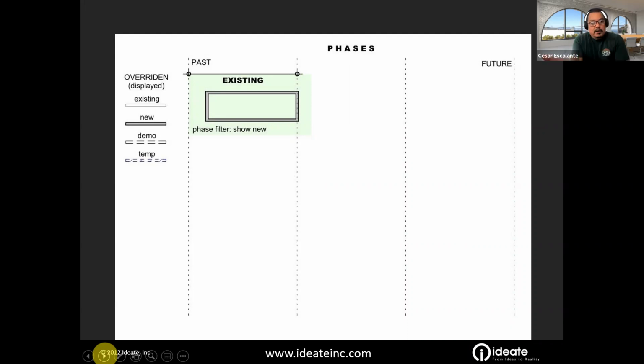And you receive a model in Revit that was created by the previous architect. When you open that model, existing conditions are shown as new because they were developed by another firm at another point in the past. But you have a new scope of work that's going to extend this tunnel in 2 different phases.